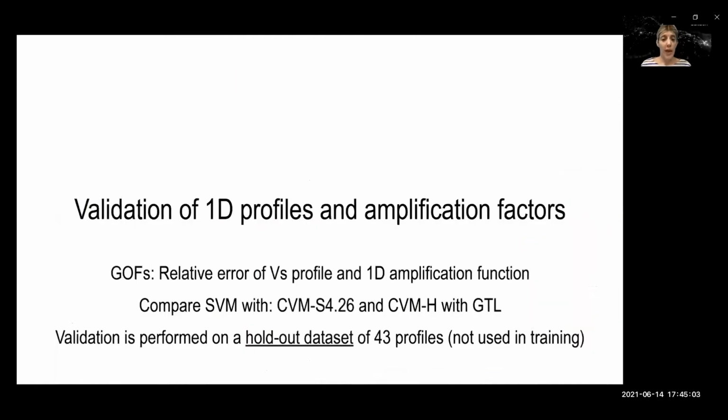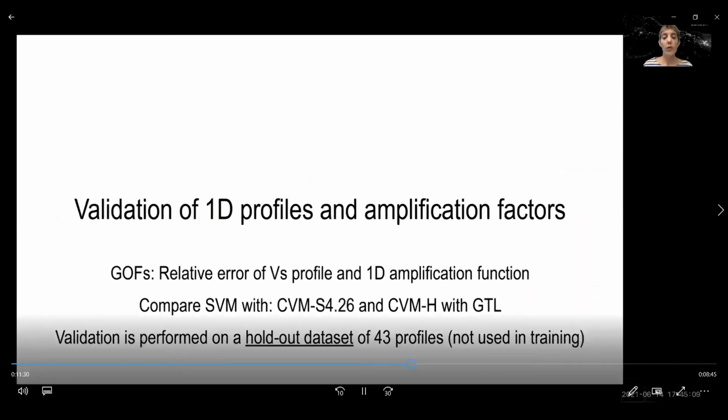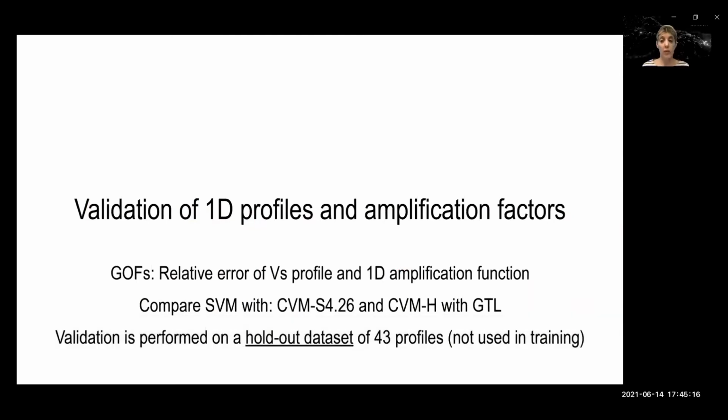So the SVM was validated using profiles from the Southern California Earthquake Center community velocity model with and without geotechnical layer. The validation was performed on a holdout data set of 43 profiles that were not used for training, and the validation was done on the basis of we checked the VS profile correlation, and we also checked the one-dimensional amplification.